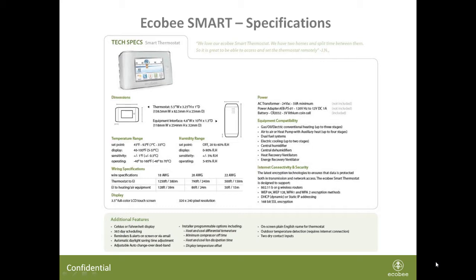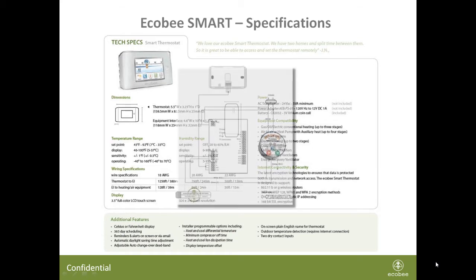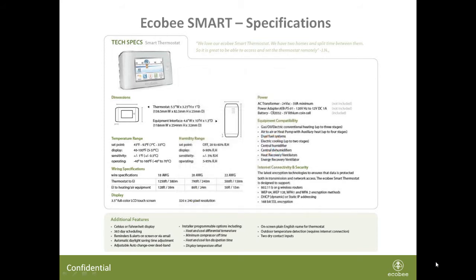The equipment interface module can be operated in a temperature range of -40 to 160 degrees Fahrenheit and can be located in attics if needed. The equipment interface module has 2 built-in dry contact sensing inputs that can be used to monitor ancillary devices like a float switch or a moisture sensor and send email alerts when triggered.